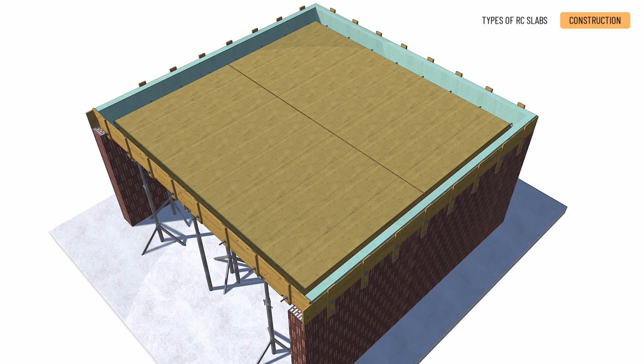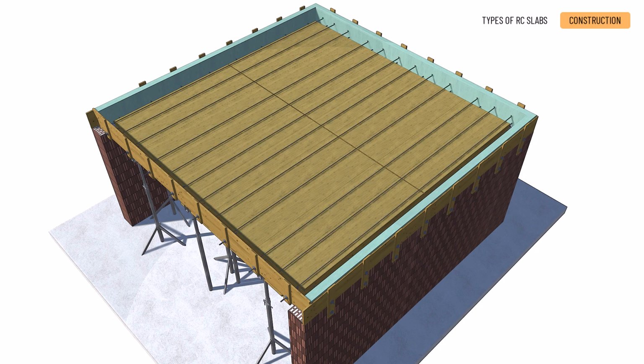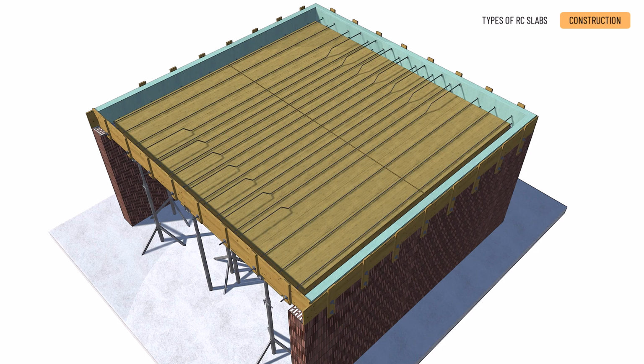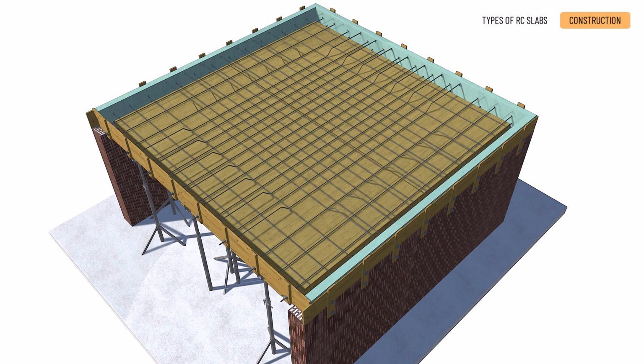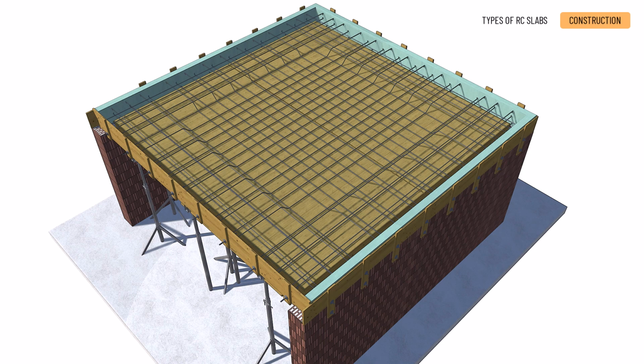Installation of reinforcement. First, place the main rebars for the base. Second, distribute the reinforcement of the base. Third, fasten two-way irons together with tie wires to create a mesh reinforcement. Fourth, position the mesh and place spacers to create the required base concrete cover.